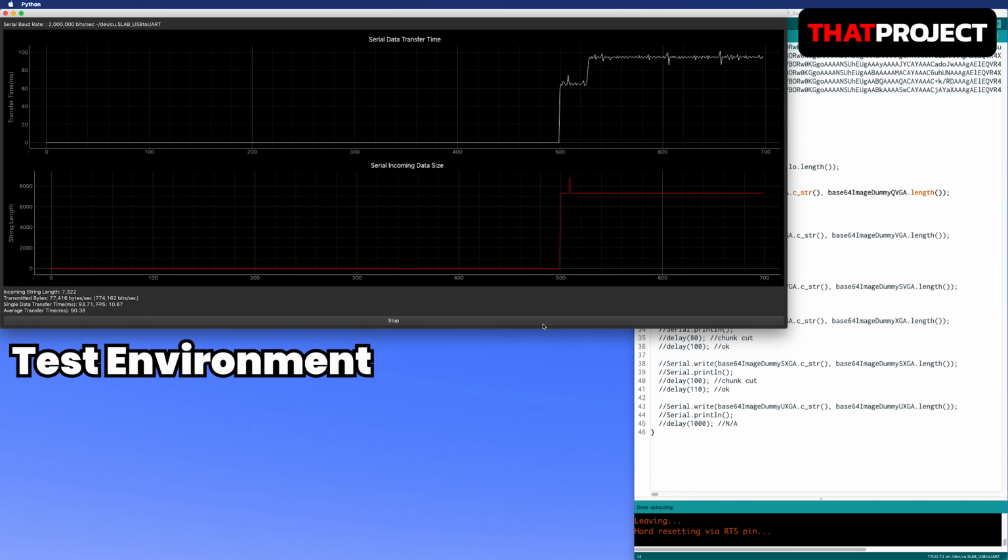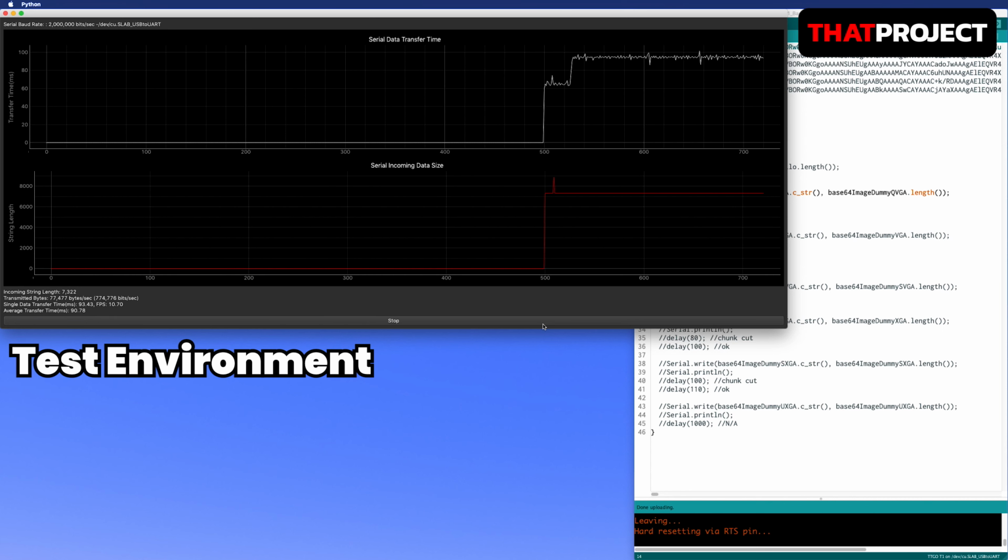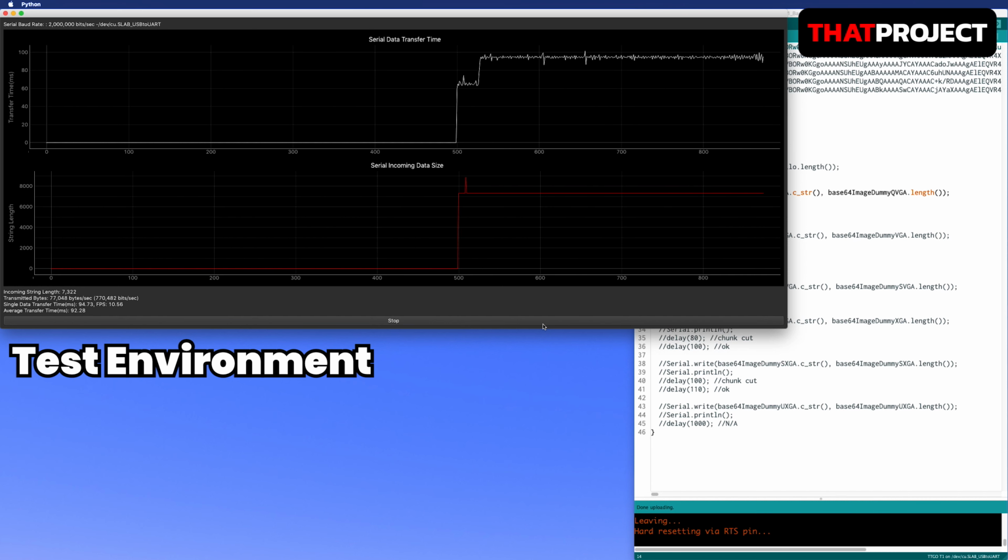If you send very large data, you can set the minimum chunk unit first, split the data with this, and then send it. You can make the original data by assembling these chunks in order at the receiver end. I tested several times to reach the maximum transmission speed by increasing the size of the chunk and delay time. Let me show you my test result.